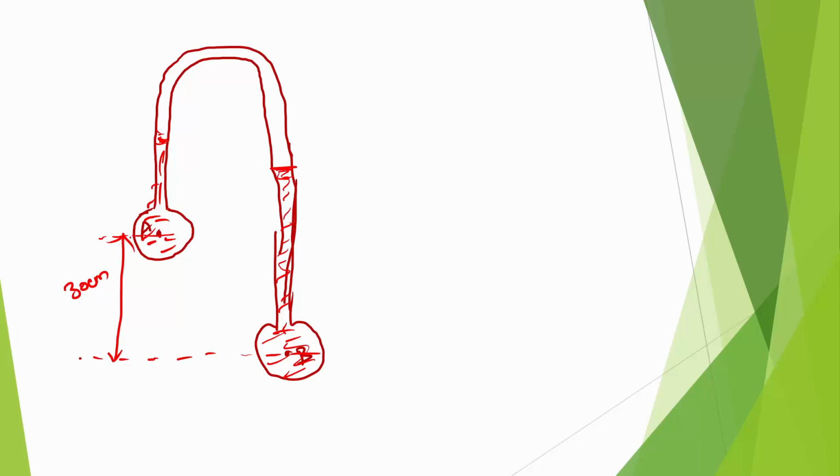Now as we know, the pressure at A will be lesser than the pressure at B, right? Because from a reference point, the more bottom I come, the more the pressure will be. So let me take this as my manometric fluid. Now as you can see, the pressure at PB is greater than the pressure at PA. So this pushes it with a larger distance. As you can see, the height from this to this is larger compared to this to this.